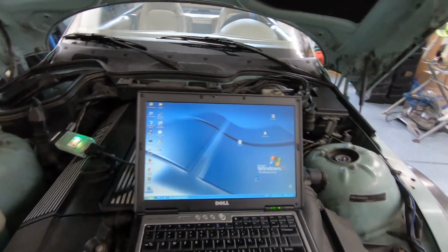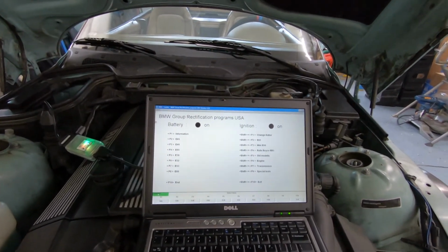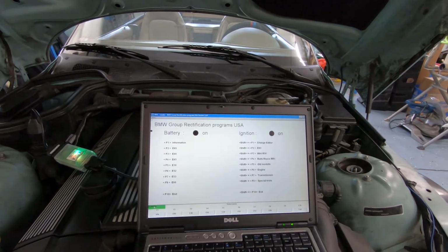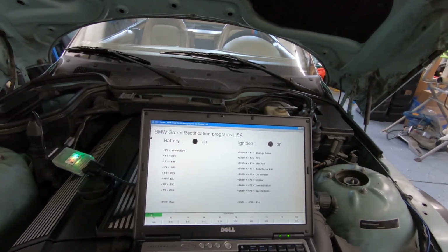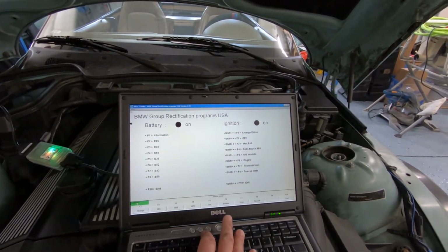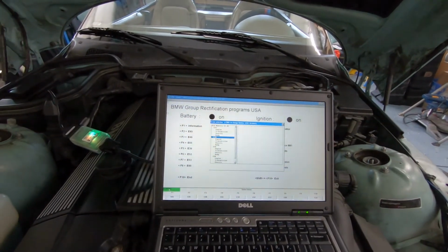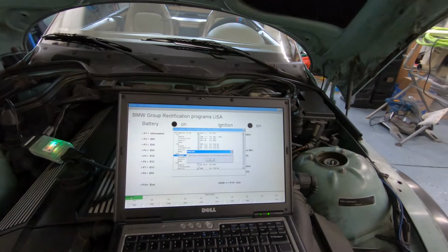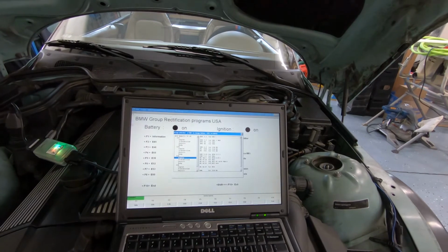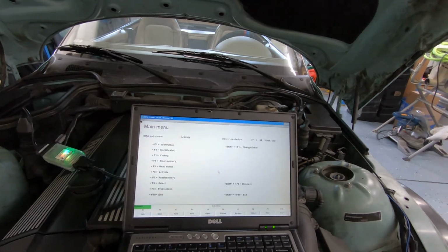Alright, and then I went into INPA. So this is based on version 6.3.4 or 0.7. You have to use the older version to work with a 32-bit system, essentially, is what it comes down to, from my understanding. So we got the Shift F5 for old models. Bam. Running E36 engine. Control module, we got the MS 41.1 with the M52 US with OBD2. That's my controller module.